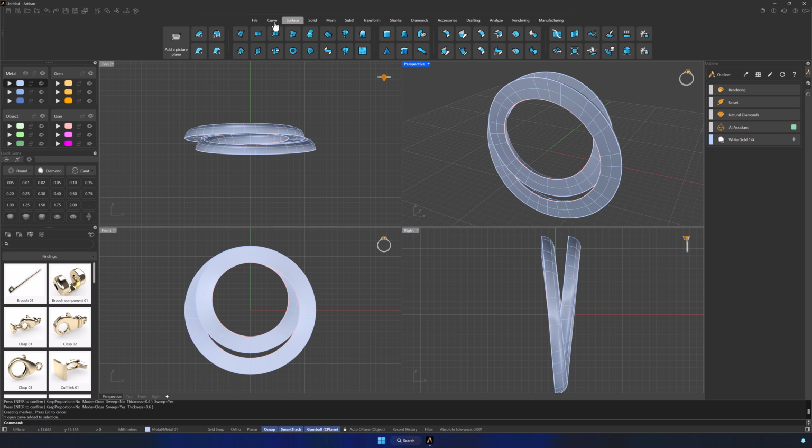Click the command again, then select the edge where the arrows point outward, Surface Edge. Since we already have an offset value of 0.5, we just need to press Enter to create the second curve. We'll move them to another layer so they are easier to see.